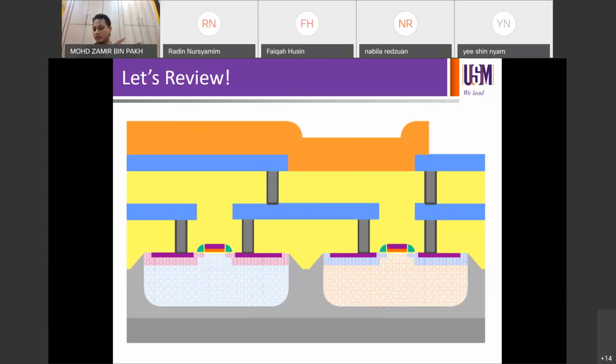What does the passivation layer do? How many metals do you need? What is the role of IMD1, BPSG? How do you prepare BPSG? So on, right? So on. So you try to explain to yourself to make sure that you understand the integration of at least this simple device. If you can tell yourself the role and the layers and the function and the process and the specs and stuff, then that means you understand the basics of process integration.